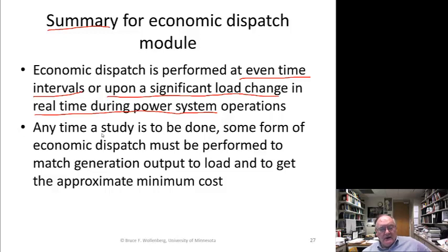If you're doing a planning study where you're looking at, let's say, adding a new generator, you're going to do an economic dispatch with the new generator to see what the total cost is going to be. Or if you're putting a new transmission line in, then you do an economic dispatch to see how the system performs. So the economic dispatch is a very basic module, very basic part.